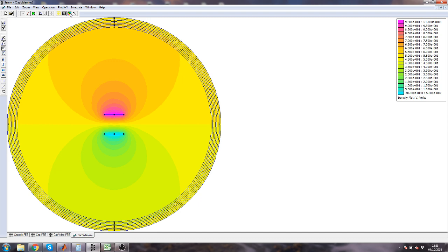Always start with something you know the answer to, in order that if you've buggered up the setup of the simulation, you'll pretty quickly realise that something's not right. If you ask it questions that you don't know the answers to, it will provide you with numbers and you'll believe them, and they might be complete garbage. So always ask it simple questions first until you're sure that the simulation is working. Then you can start to experiment on the things you don't know the answers to.